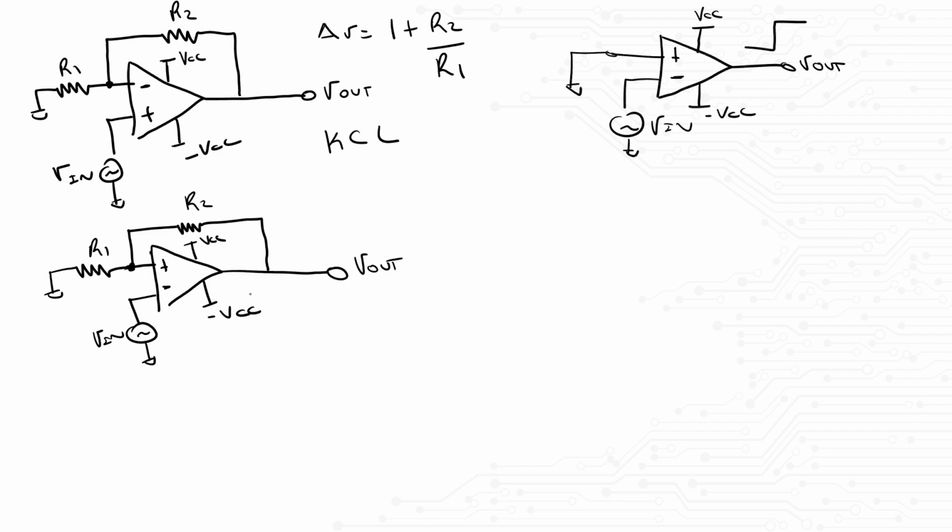Now, let's tell the interviewer what our plan of attack is. In this case, you can say something like, the transfer function is nothing more than what Vout I would get for a given Vin. If I start with nodal analysis, I am going to need extra information. So let me call this node right here X. The other input is Vin, but since we are not in negative feedback, we cannot assume that Vx equals Vin. For now, let me continue to call it Vx and move forward.